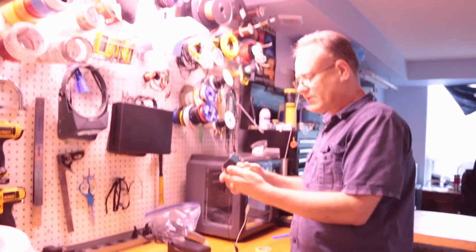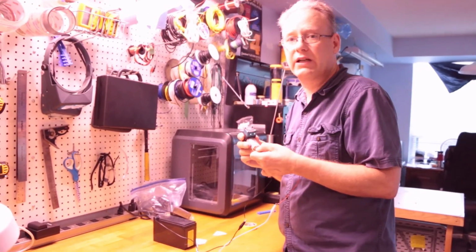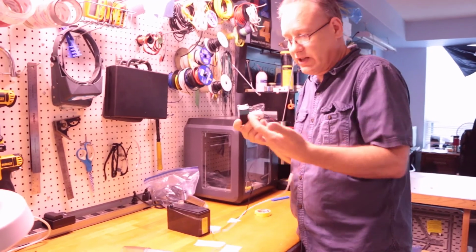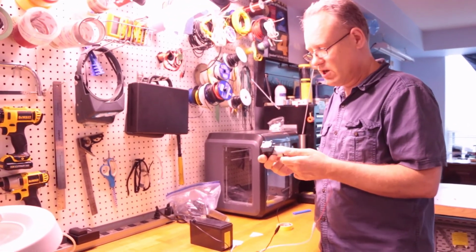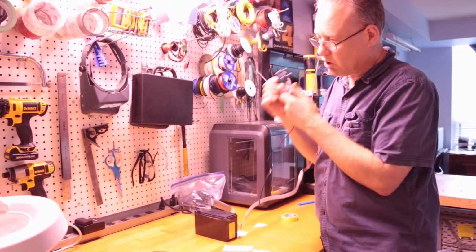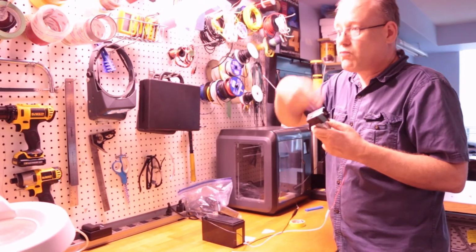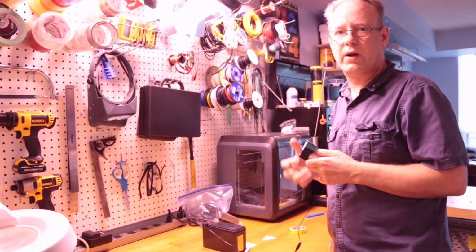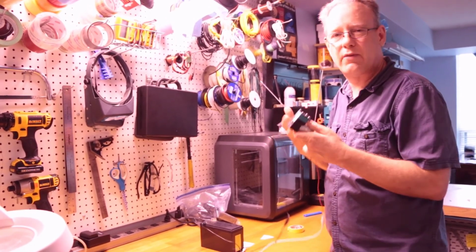Reciprocating pumps will generate the highest degree of vacuum. If you need, scientifically, a ridiculously high vacuum, then you can get a two-stage vacuum pump as well, just like we have a two-stage compressor. So these produce a lot of pressure and very little flow rate. A rotary pump can generate a high amount of flow rate with lower pressures, but sometimes that's okay, or sometimes we need that when we have a poor seal.